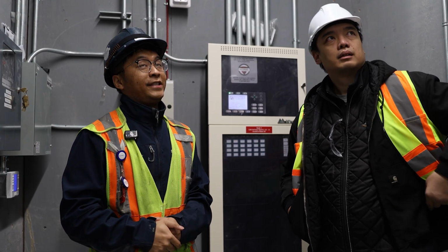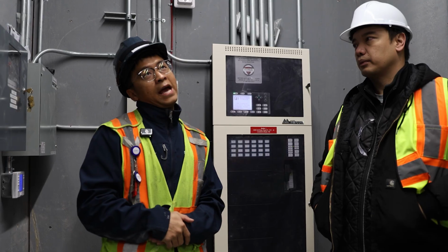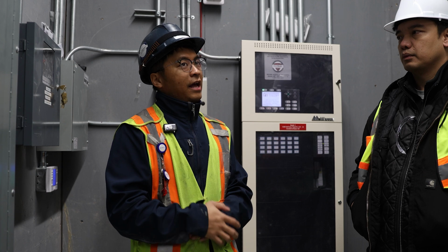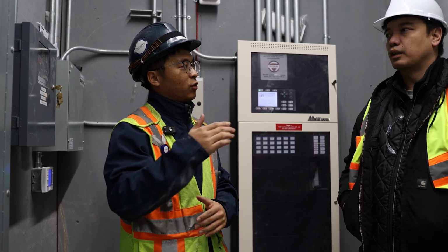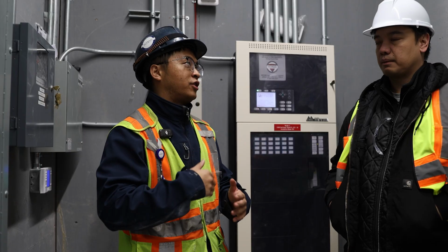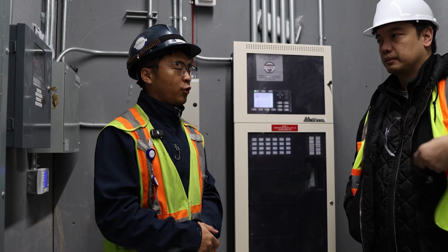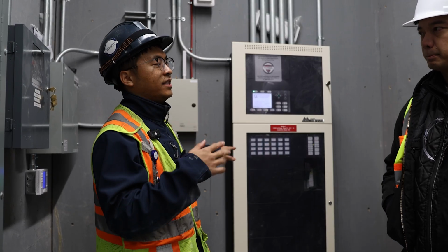And you will also see the loop temperature on the supply and on the return. Most likely it will work, but the heat pump will just be underperforming if the loop temperature isn't maintained well. Yes, you can see the loop temperature, and we also have a trend set up. You can see the loop temperature for the past 2 weeks.